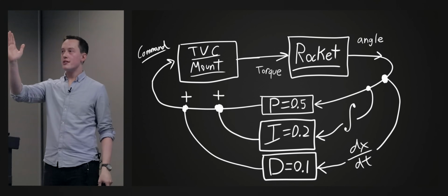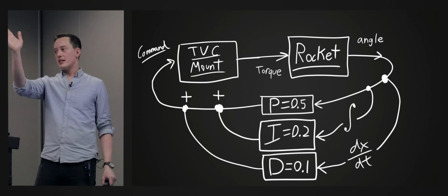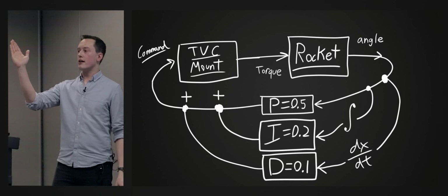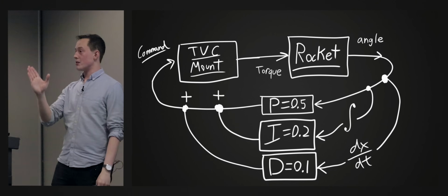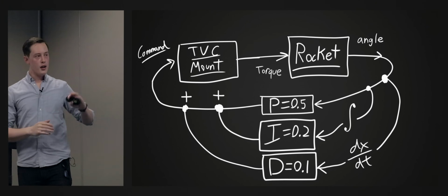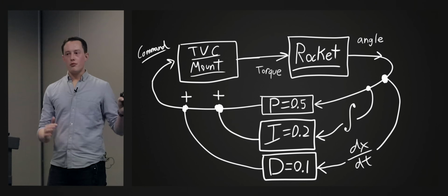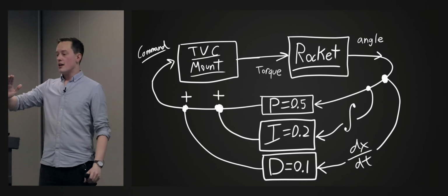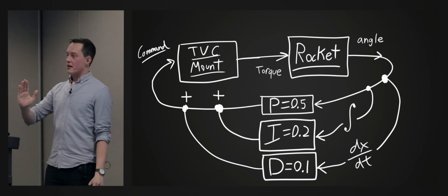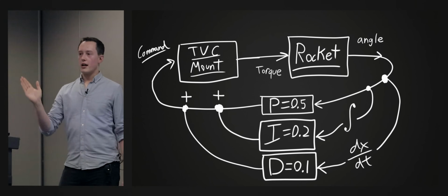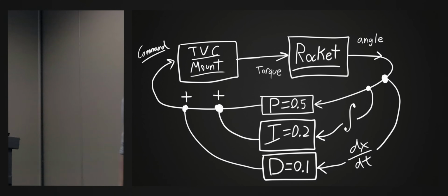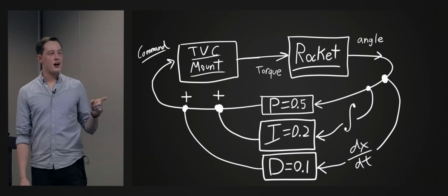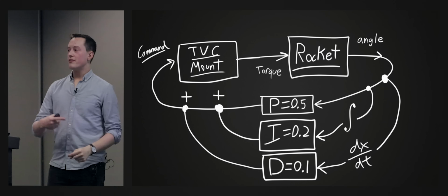When the rocket launches, it's going to be arcing over just a little bit, but those P and those D gains are going to correct for it. But you're going to stabilize around a point that is probably closer to like 1 or 2 degrees, right? Regardless of what those actual values are, you're not going to end up at a straight upright point, because when the mount actuates to get rid of that misalignment, your vehicle is going to be tipped over. And the control system, if I get rid of the I, has no way to correct for that.